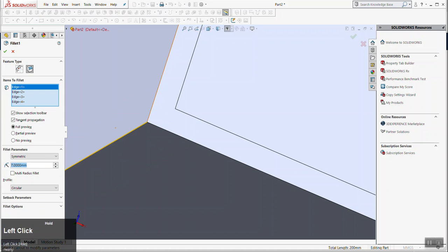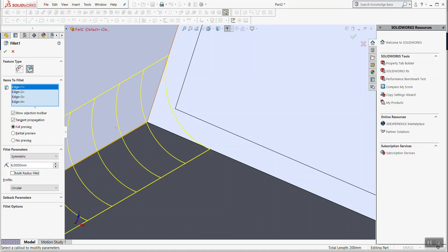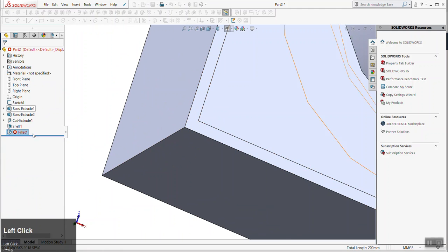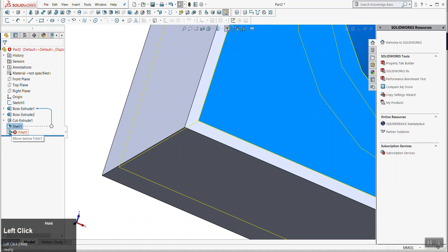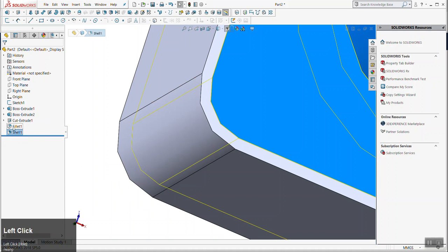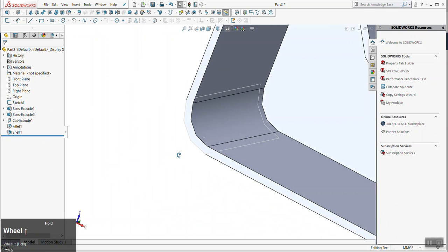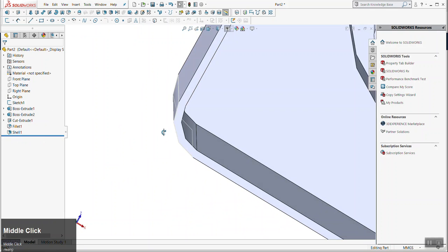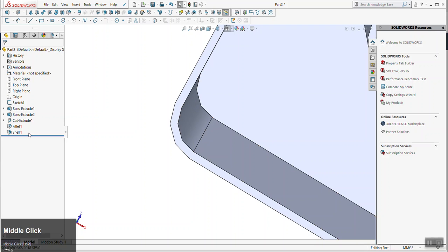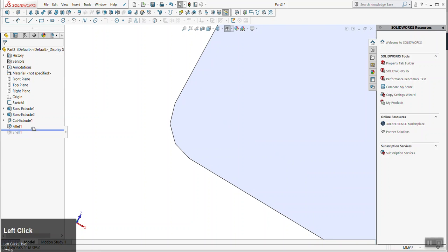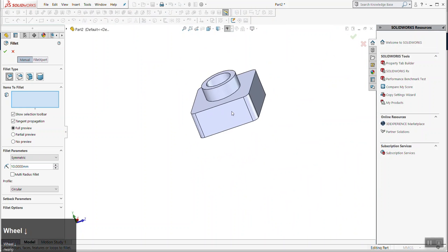No, 6. This is a game you're all going to play at some point in this class: what is the largest fillet I can get on this corner? This is a very common game to play. There's more advanced stuff, but we won't get into it. Anyway, labored point, if I drag this shell now below here, now it fixes it. Because when it shells, it checks the outside surface. Now it can create an inner fillet that matches that. So in this instance, you want the fillets as low as possible. Sometimes you need other commands to go beneath it.